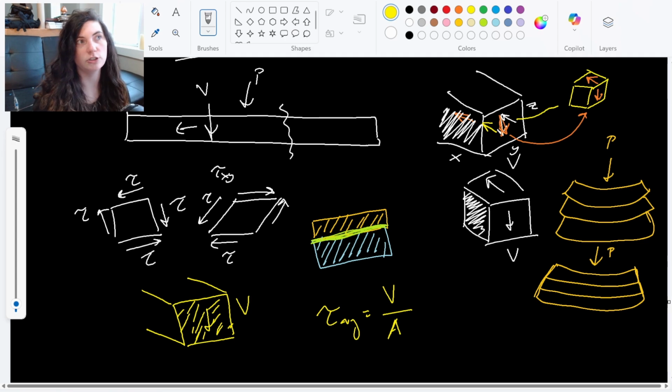It works a lot like our torsion, where we had no shear stress at the outside, and then as you got closer and closer into the center for something under torsion, that did have shear stress, that's our maximum shear stress as we got to the center. So that's exactly how shear stress works in beams. It's not constant all through the beam. Instead, our shear stress is really small, and then it gets bigger, and then smaller and smaller.